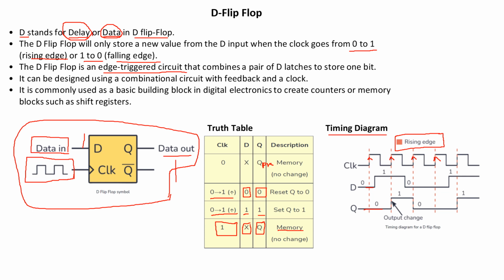It will only get updated at the rising edge. So my data will be low, and at this rising edge you see the data is logic high, so I will transition from 0 to high. Again it is logic high only, and at the next rising edge my data is low, so my data will transition from 1 to 0. So this is my Q output.